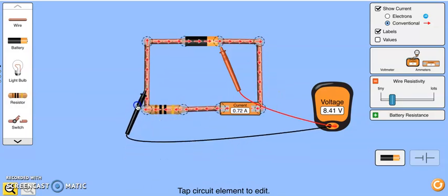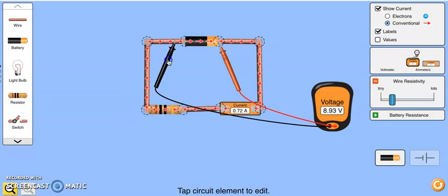And then as I go more and more wire, eventually I get to the 9 volts. Now, this assumes something about the battery itself, okay, and that is that there is no resistance in the battery. We're going to treat our voltage sources as ideal, and ideal means it has no resistance. We'll eventually come back to investigate what happens when it does have resistance.